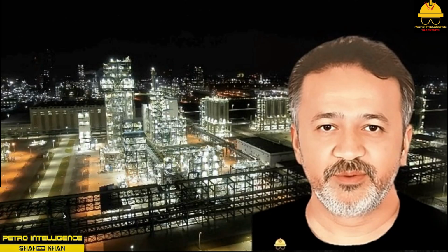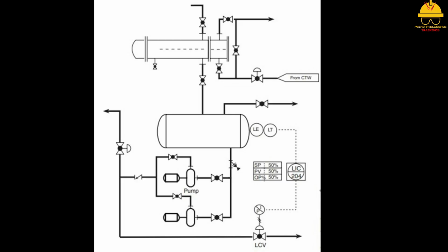Level control loop. The following example of a level control loop can easily be applied to level control on any vessel or tank. Level control uses floats and float gauges, displacers, tapes and tape gauges, differential pressure transmitters, bubblers, load cells, capacitance probes, electromagnetic measuring devices, and nuclear measuring instruments. This picture illustrates what a standard control loop looks like.